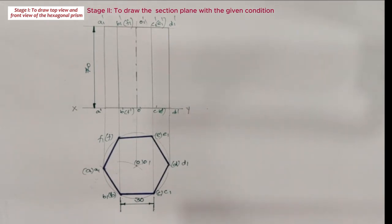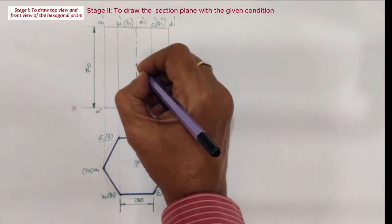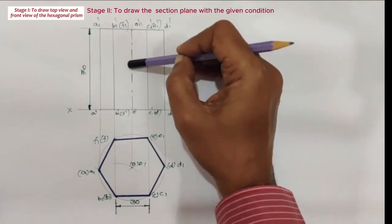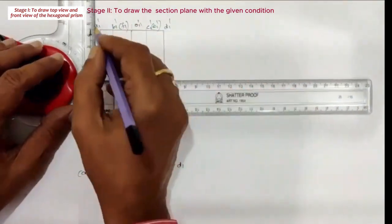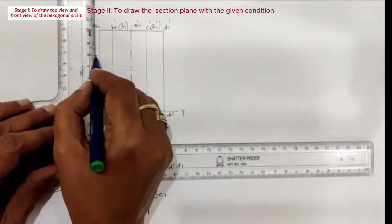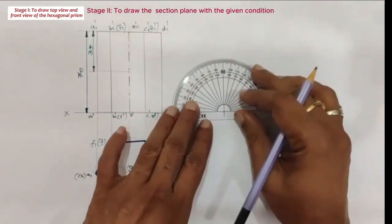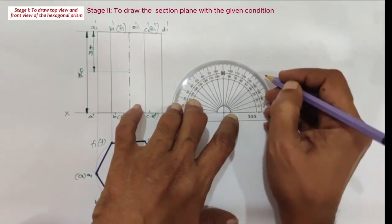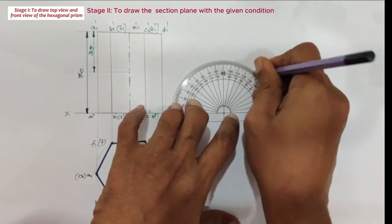Here, the section plane is inclined at 45 degrees to the HP and passing through the midpoint of the axis. Here, the total height of the axis is 70 mm. Then locate the midpoint of the axis. The section plane is making an angle 45 degrees to the HP. So first draw a 45 degrees inclination line to the XY line.